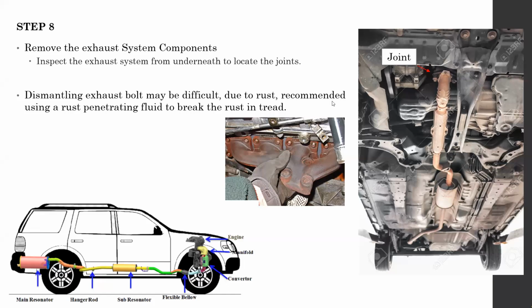Okay, so where was I? Yes. So the exhaust pipes are usually rusted. To tackle this issue, usually we use something like a rust penetration fluid. Rust penetration fluid is somewhat similar to the WD-40 you might have heard of. WD-40 is not for rust issues, it's actually for seized up nuts and bolts, but it works to a certain extent for rust also.